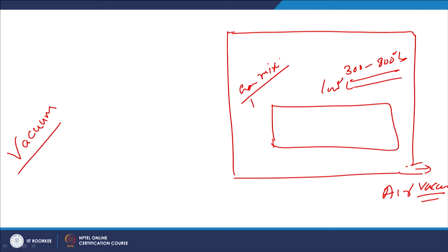It can use plasma, ion beams, or any other material which is to be deposited in the form of atoms. Such a suitable medium is made available around the surface of the component which is to be modified, at a reasonably low temperature and for sufficient time.